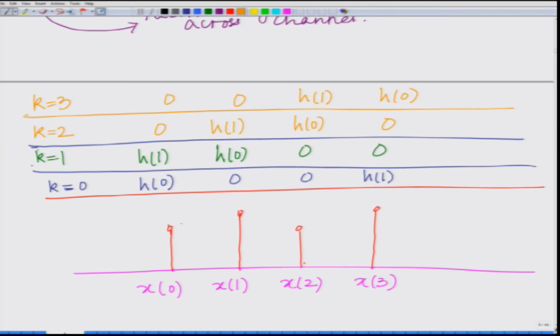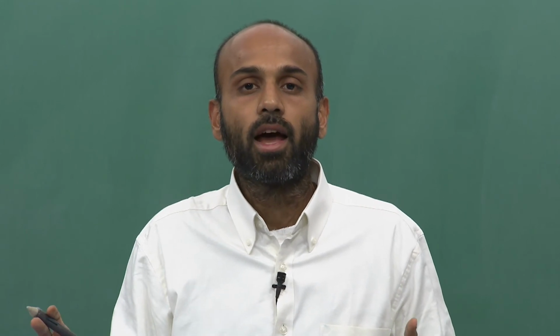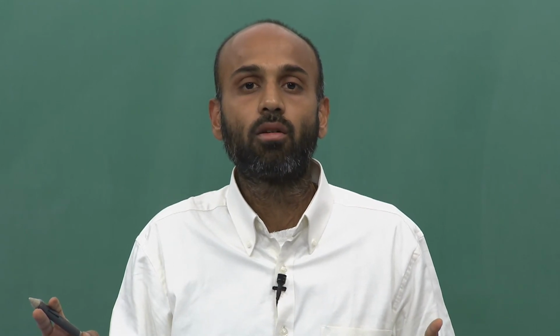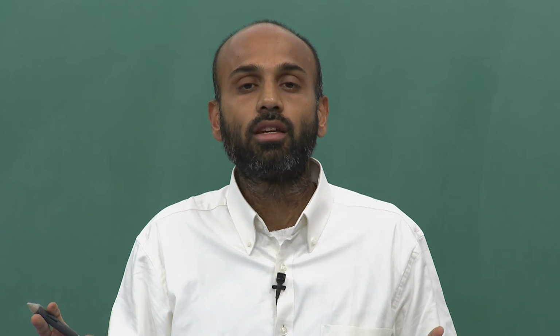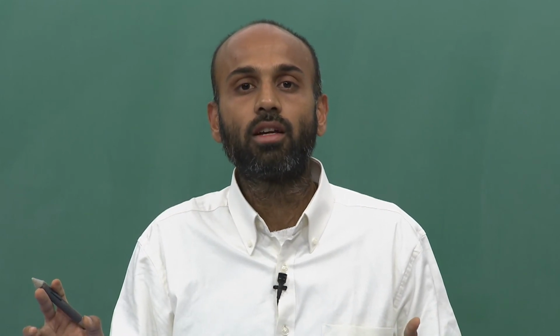And now as you can see, if you observe this figure closely, I have the symbols x0, x1, x2, x3, and the channel taps, or the channel filter, H0, H1. You can see that the channel filter is rotating over the transmitted symbols.